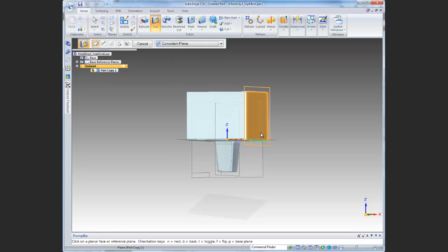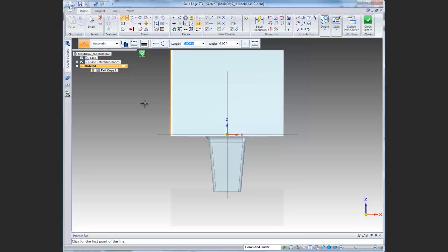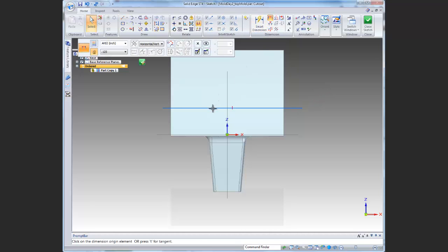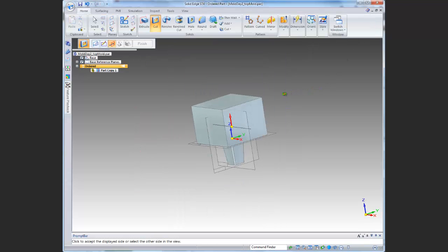So what I'm going to do is I'm going to do a cutaway. I'm just going to put a cutaway line on the front. Lots of ways to do cutaways. I'm just going to make a line that's horizontal. And I'm going to say make your distance from here down to there be exactly 3 inches. So that looks lovely. Now it's asking me which side do you want to cut away. I want to cut away the top.